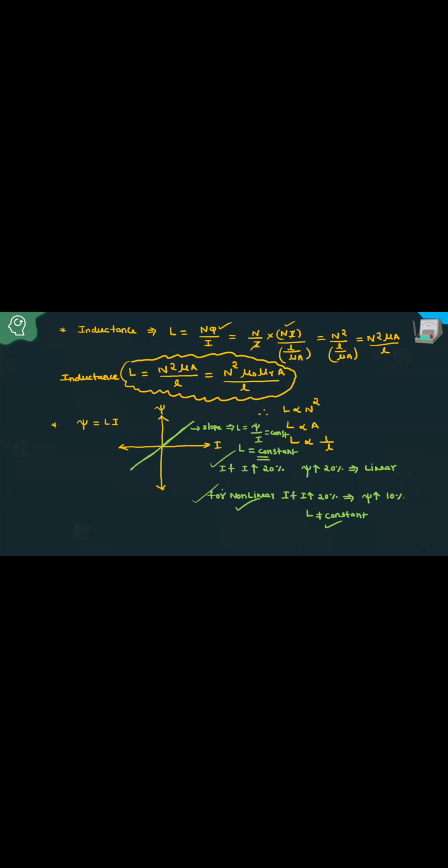If I is increased by 20% and psi is increased by 20%, then we can say that this is linear. If I is increased by 20% but psi is increased by 10%, then L depends on I and psi. That's the reason we say it is non-linear. Okay, this psi equals L i formula you also have to remember. This is one formula used during solving of problems.